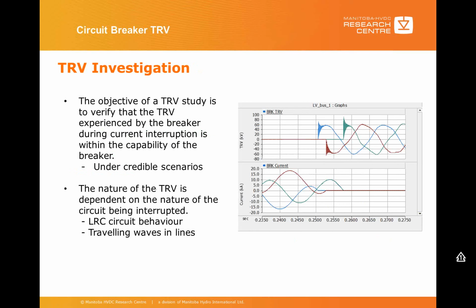Generally, the objective of any TRV investigation is to verify that the TRV, or the recovery voltage, experienced by any breaker upon current interruption is within its capabilities.